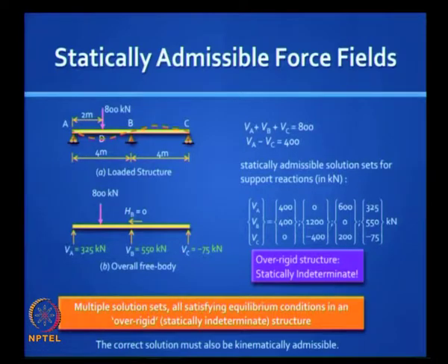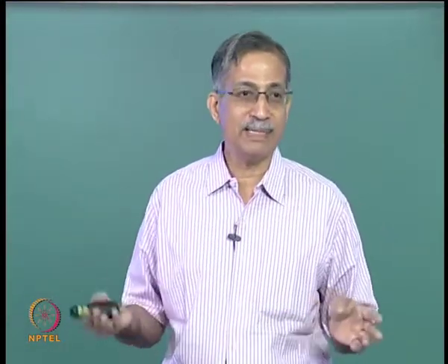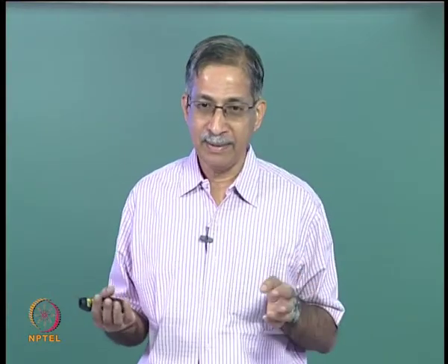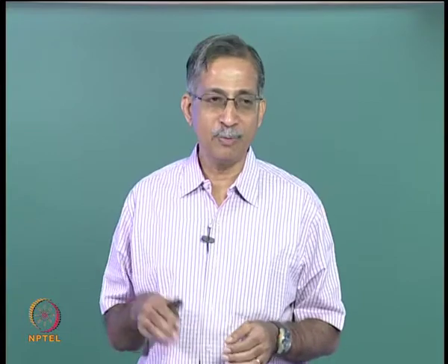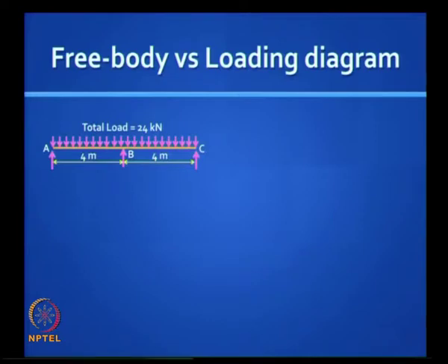You will find that if your structure is statically determinate, you do not need to explicitly satisfy compatibility, it gets automatically satisfied, it is enough to satisfy equilibrium, and you can prove this. We will come to the proof when we study matrix methods subsequently. At this point I want you to realize that when we draw diagrams like this, we tacitly assume that A, B and C are support locations, that is, these are reactions, but this diagram does not reveal anything, and it is necessary to know how to distinguish between a free body diagram and a loading diagram.